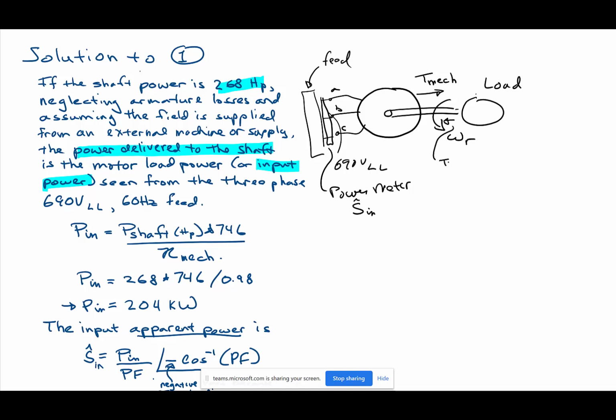You can write them even in terms of a torque loss, but not all of the torque gets to the load because of these losses. A lot of times, for example, they have a big fan on the shaft to cool the motor. That's a loss. There's friction and other things like that, the bearings, things like that.